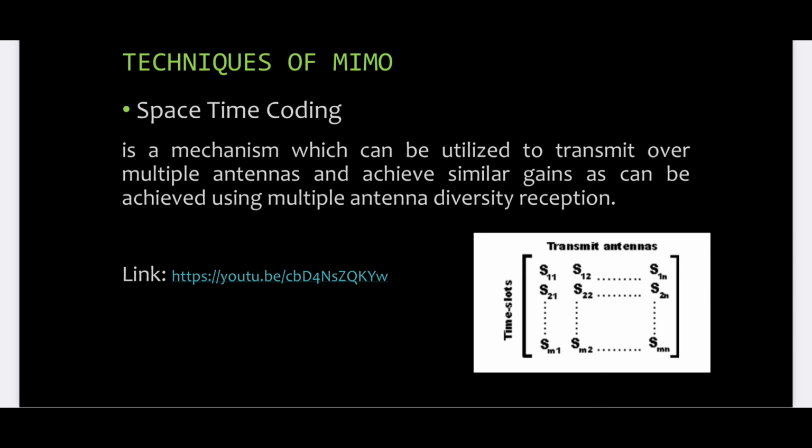Space-time coding means taking the data which would ordinarily be transmitted from a single antenna and applying a signal processing coding technique in order to transmit a mathematically altered version of the same information content on additional antennas in a way that enhances the ability of the receiver to separate the data from the background noise. Space-time coding can be a natural match to receive beamforming or diversity reception.